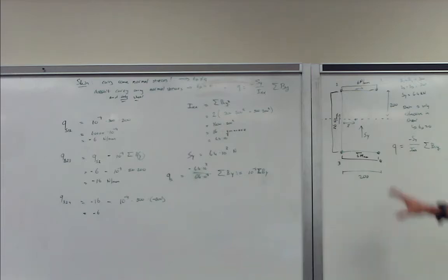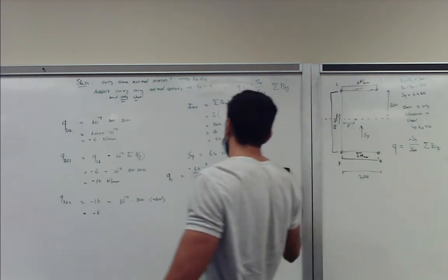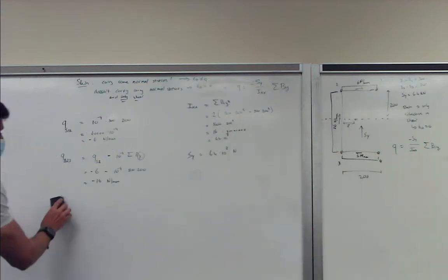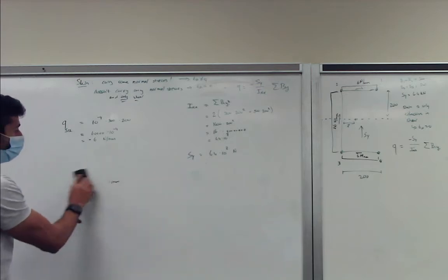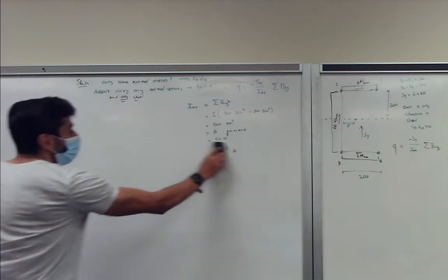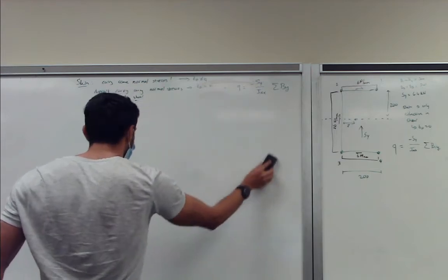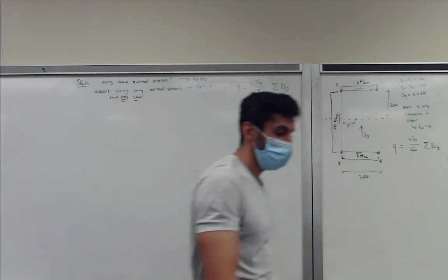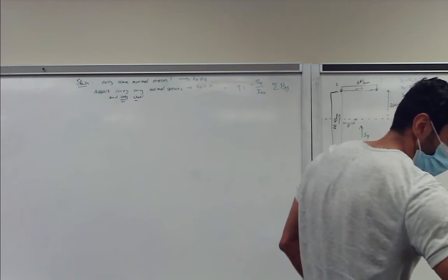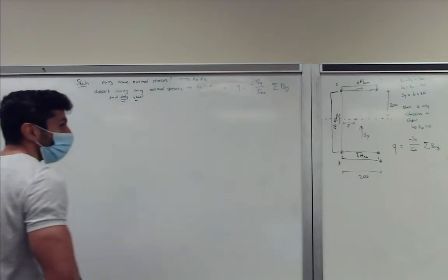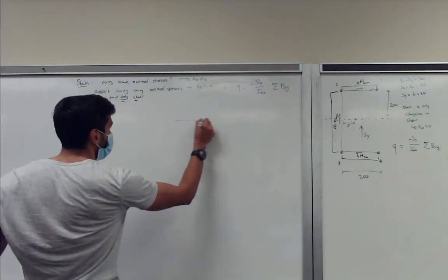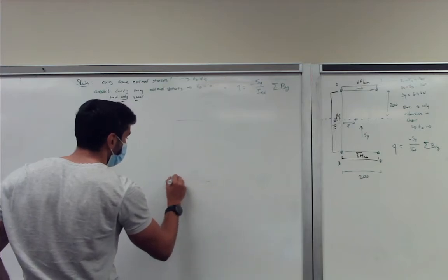Okay, so let's redraw this figure and let's recall what our previous figure looked like when we did it without the boom assumption. As you can see, now the shear flow equation becomes actually easier because it just becomes a summation of the boom area B multiplied by the distance y. So let's redraw some of our figure. This was our cross section.